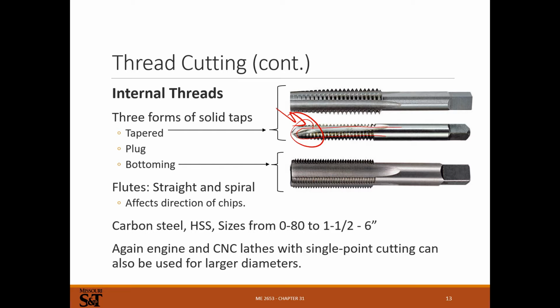You have to use some kind of cutting oil in almost all cases, and usually a specialty cutting oil like Tap Magic. In fact, I don't know any machinist that doesn't use Tap Magic. Every machine shop I've ever been in has aluminum Tap Magic and regular Tap Magic. For aluminum threads, you always use aluminum Tap Magic, and for steel, you always use regular Tap Magic. I'm not a salesman for Tap Magic, but I've never seen a machine shop that used anything else. Regular cutting oil, people just don't seem to use. So there's probably a reason for that, and it's probably because it works.